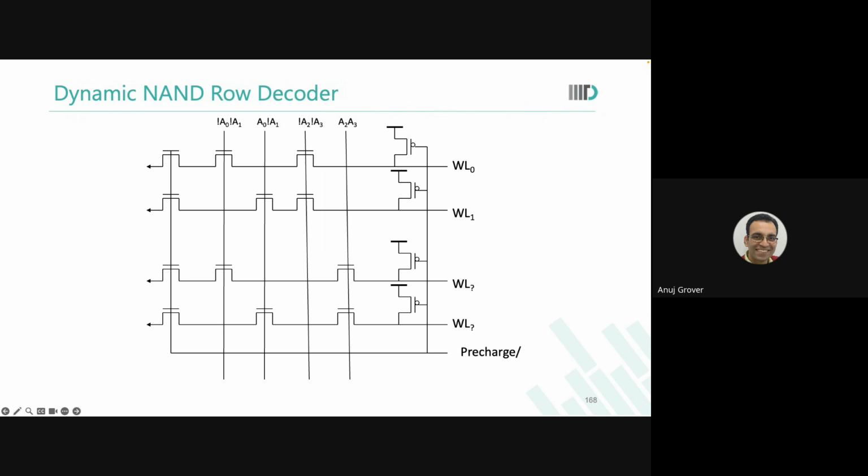Yes, many things will change when you use a negative bitline circuit. You're already operating at a low voltage. That is why you needed negative bitline. So timing degradation is anyway going to happen. But the fact also remains that negative bitline will result in a faster write time inside the memory cell, so that would also help you recover something. So it's no one thing that you can say about a memory, Madhav.